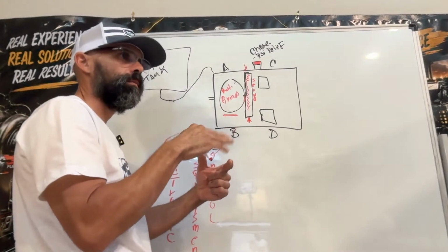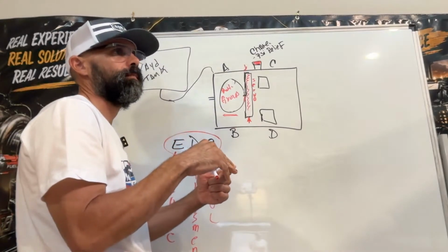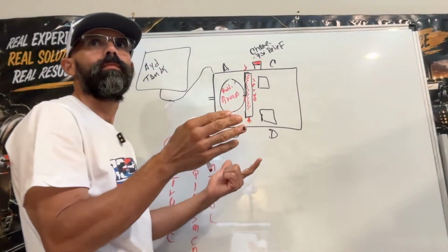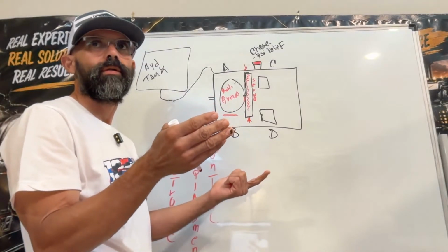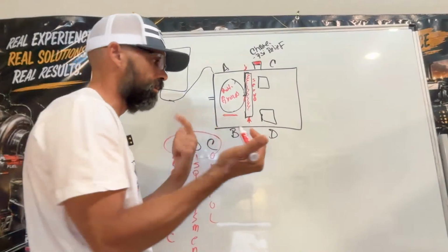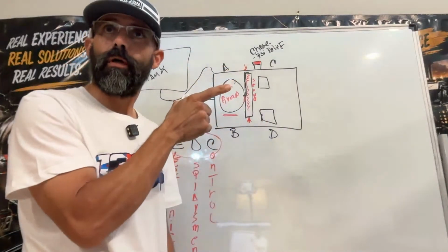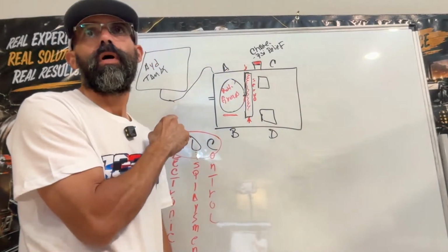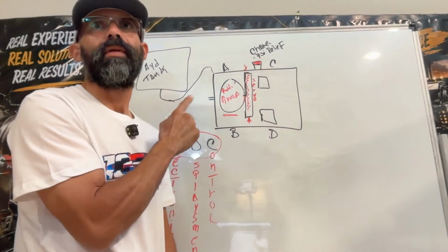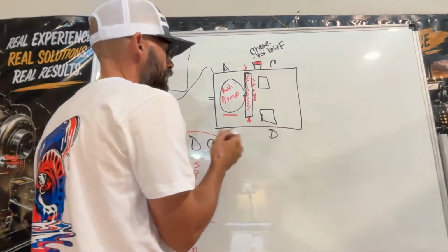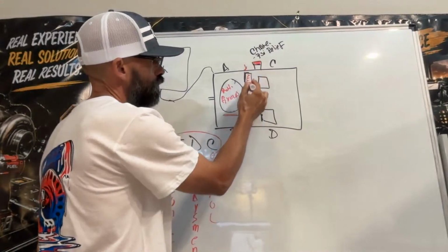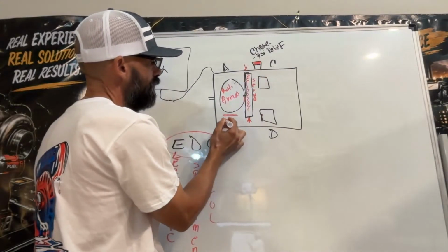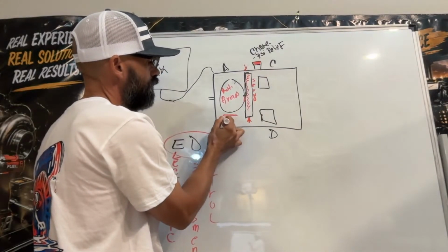That way you can lubricate and not lose any oil and not have any internal leakage. You're still going to have some. We're going to talk about why it's essential to have charge pressure, how you can detect it, and make the necessary adjustments. So that's neutral. And then as you move the EDC, the swash plate can go this way.